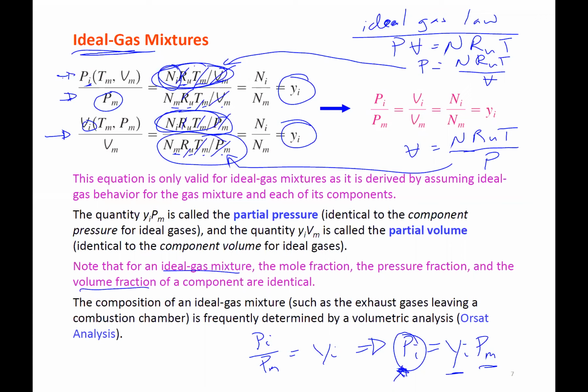When you're measuring gas fractions, say exhaust gases leaving a combustion chamber, or taking a sample of an exhaust stack, maybe from a natural gas boiler, a lot of measurements give the fraction directly. The mole fraction is what they give you, and then you use that to convert to whatever you need. The instrument would give you the mole fraction of that component. So if you have an instrument that measures CO2, it would give you that CO2 measurement.